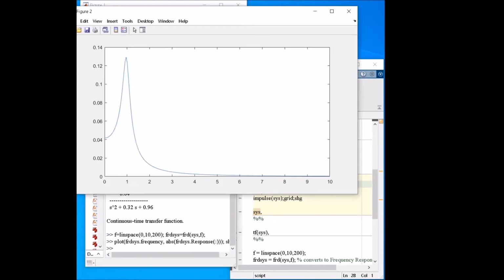Okay, here we plot the graph of our frequency response function for the second order differential equation of the mass spring system. Those who study vibration analysis can immediately understand all the behavior of this system, because this is the static stiffness, this is the resonance frequency, and this is the reaction of our response function for input frequencies much higher than the resonance frequency.